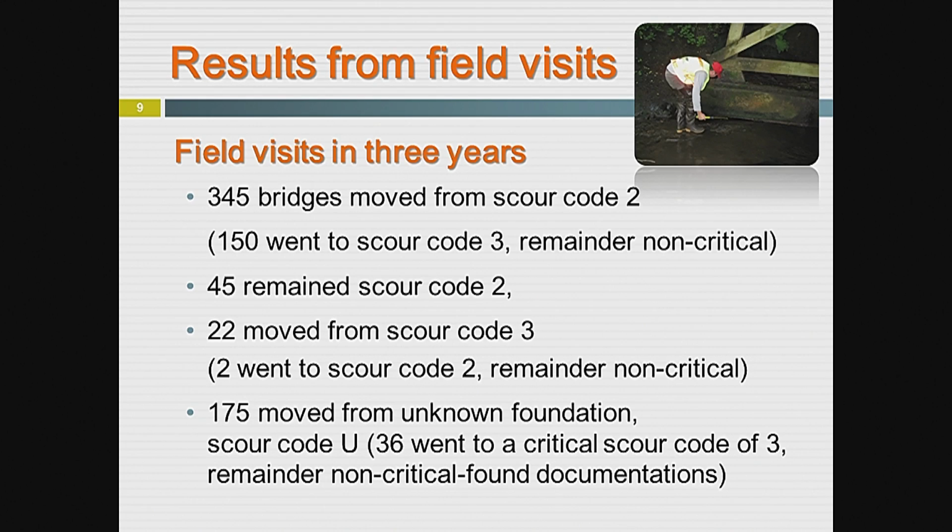So that's the thing about Scour Code 2. It has an upside. I mean, it is bad that your bridge is bad, and there's no question about that. But because FHWA says scour is 2, the substructure turns 2, and the sufficiency rating drops like lead, not like a balloon.